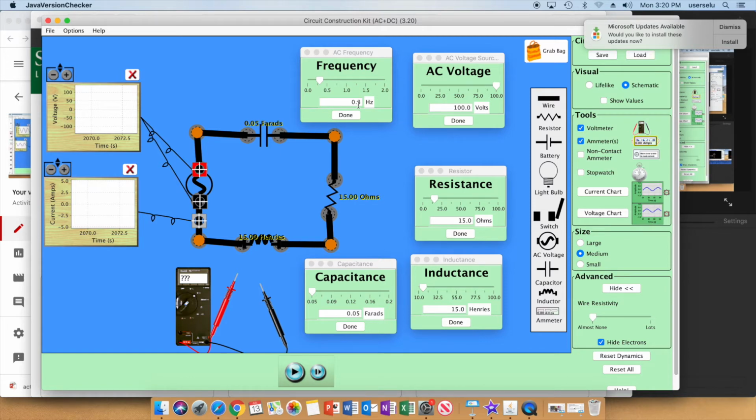Okay, now again, these components are connected in series, but you don't sum their apparent resistances because of the phase difference of their relationships. The capacitor and inductor are 90 degrees apart from the resistor, so you have to do some kind of Pythagorean relationship to connect them together. But interestingly, the capacitor and inductor are 180 degrees out of phase. Again, look at the slides to get a little more background on that. So literally they work opposite of one another. While one is charging, the other is constantly discharging. It's really interesting, and we'll touch again on that in our next examples as well.